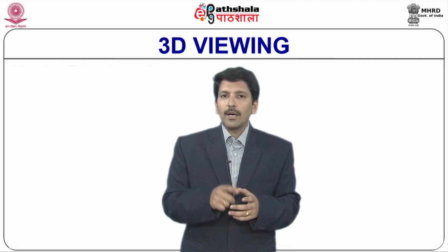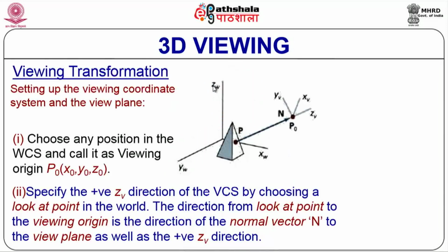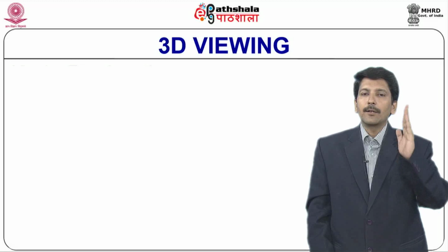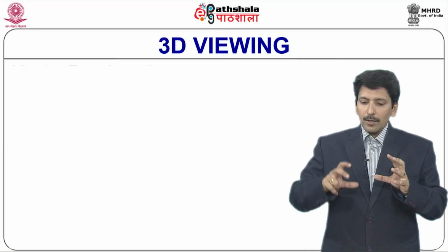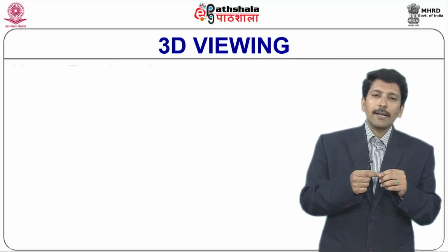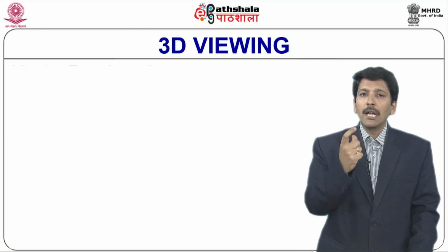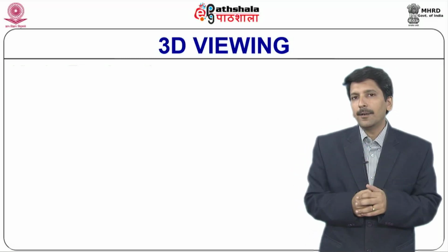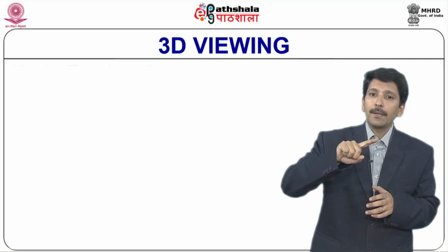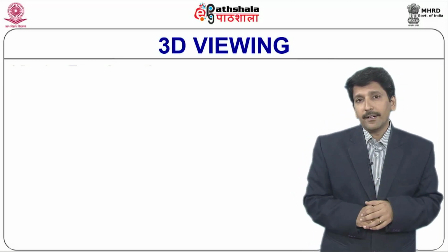Now the next step is to identify the remaining two directions, which are x and y. So our aim is to find three mutually perpendicular directions. How do we get the x and y? Before we go to x, we will do y. Y is generally considered to be a direction perpendicular to the z direction, but because we are in a 3D world, we cannot exactly identify what direction the y direction can be, because we are not still aware of our orientation. So we cannot readily identify the perpendicular direction y, which is exactly perpendicular to z and x, because x is not known, so y cannot be perfectly identified.